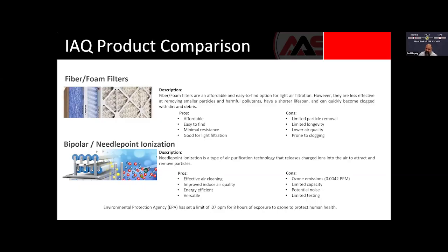If you can fit a thicker pleated filter on your unit, like a 2-inch or a 4 or 5-inch, which usually requires a separate filter cabinet, it's highly recommended because you can get more filter surface area, allowing your unit to not be restricted, but also gain the functionality of the higher rated filters like a MERV 13, where you can filter down to the actual virus carriers. So I always recommend pleated filters for your units.